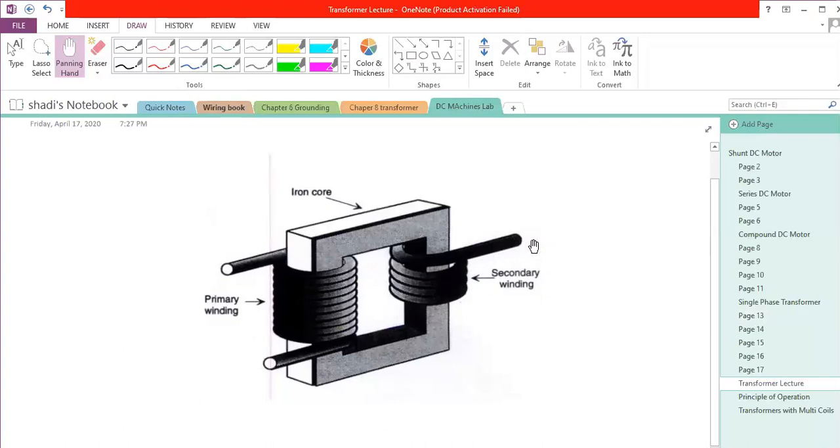Now, in this case, this side of the transformer will be the secondary, so it will generate a voltage, and this voltage will be double the voltage that comes from the primary. So if we have 100 volt here, we will get double, because as we stated, the number of turns here will be double. So the voltage we will get at this secondary will be 200 volt.